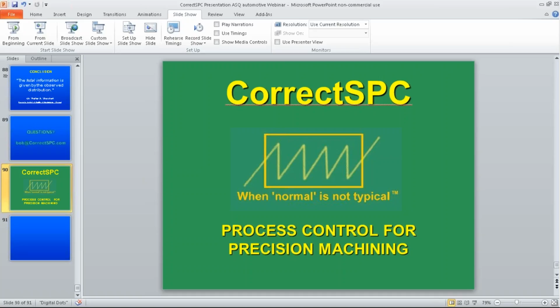Here's another question. Sometimes I try reaction limits versus control limits, just to differentiate control limits as being calculated, and reaction limits might, for example, be 75% of the spec. An out of control situation might be when there is a significantly faster or slower rate of movement or a significant change in roundness. Are there similar rules for the high-low chart beyond making an adjustment when you hit a limit?